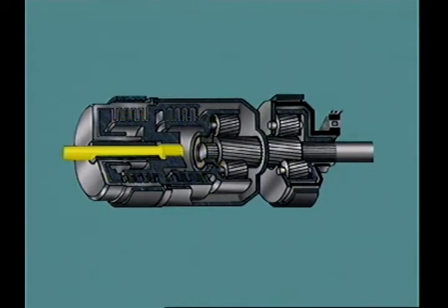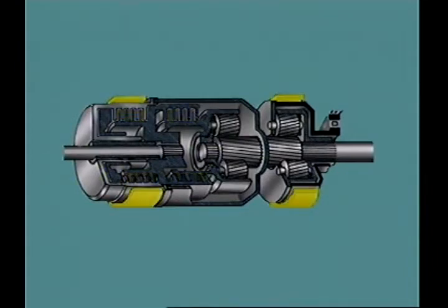The input shaft is separate from the gear set. The drive is transmitted through one or more clutches, depending on the gear and range engaged. Two bands and a one-way clutch are also used to control the gear set components.